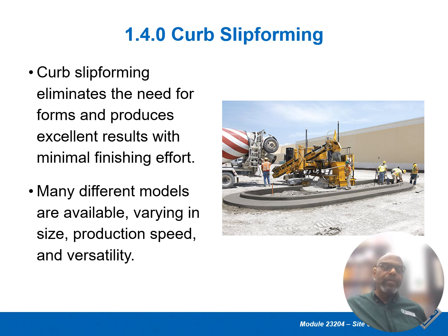Curved slip forming again eliminates the need for forms because the machine itself is the form. It makes the concrete in the shape you want it and produces excellent results with minimal finishing effort. Many different models are available, varying in size, production speed, and versatility. So again, that machine can really put out curves very quickly.